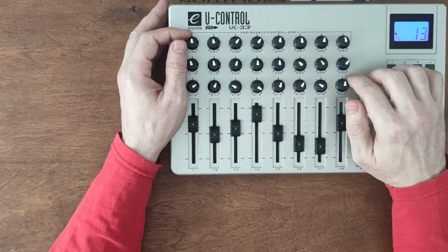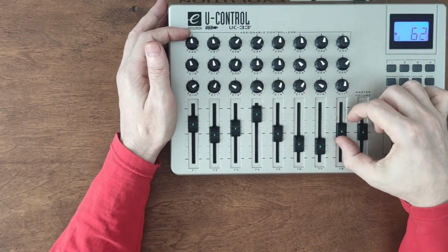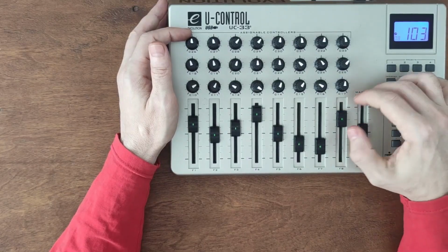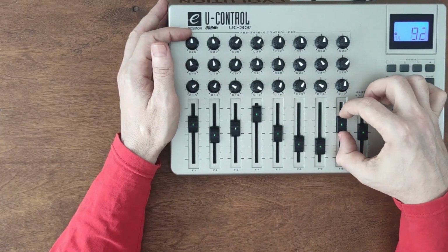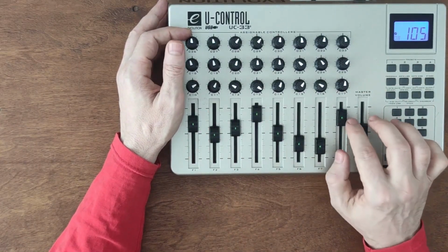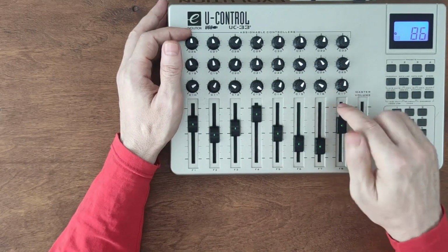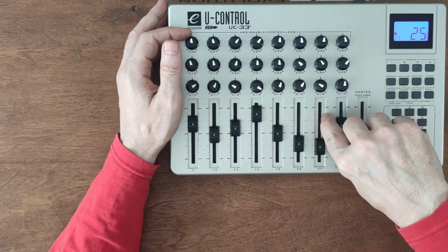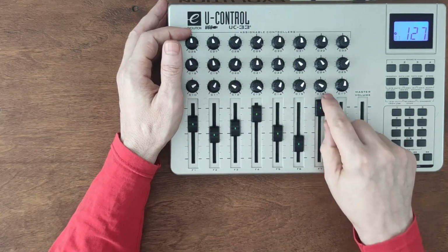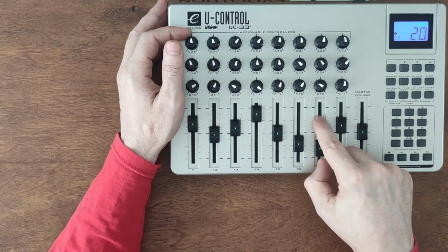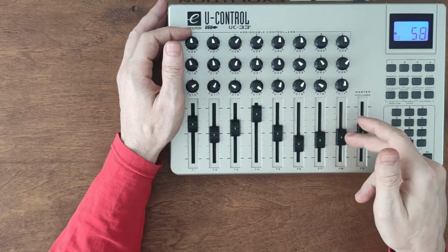As for faders, if you find the faders generating spontaneous behavior, you need to desolder the faders and clean them from the dust which got inside through the fader control moving entrance, the hole of the fader.